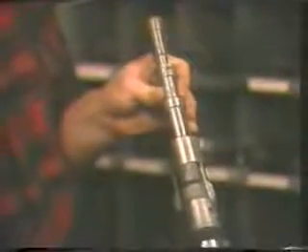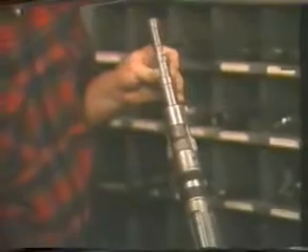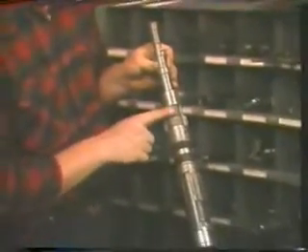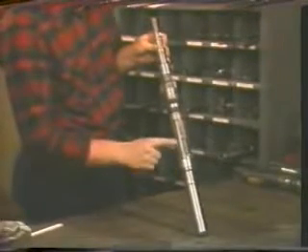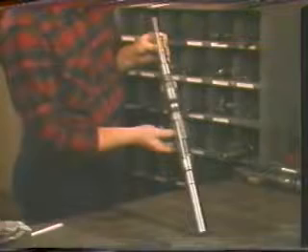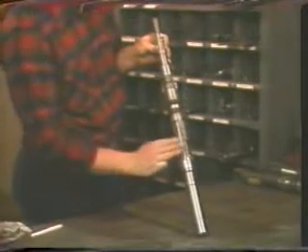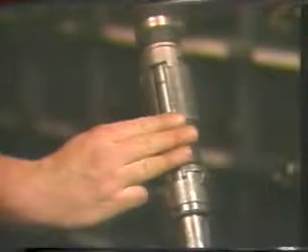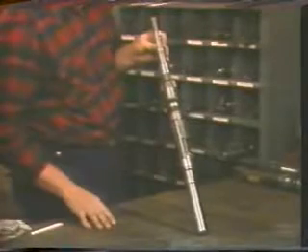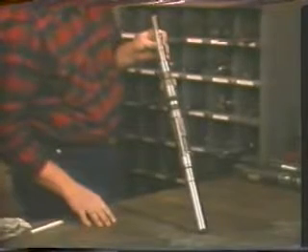The Type S lock mandrel consists of 2 sub-assemblies, the locking assembly and the locating assembly. 5 different profile keys corresponding to the profiles in the 5 positions of nipples may be incorporated into the locating assembly. For example, if the locator keys used on the locator are position 3 keys, then the lock will only locate in the position 3 nipple. This is how the lock is able to select the nipple in which it is set.